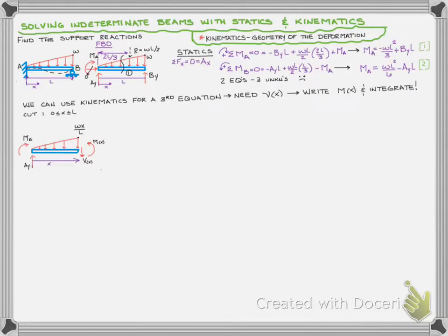Let's jump in to where we were at, and now we're ready to do our statics. We'll want to find our resultant, which would be at 2/3 of x from the left side, and we'd have Wx over L times the distance x times 1/2 as our resultant. If we sum moments at the cut, we don't have to find the shear at the cut, it just goes away.